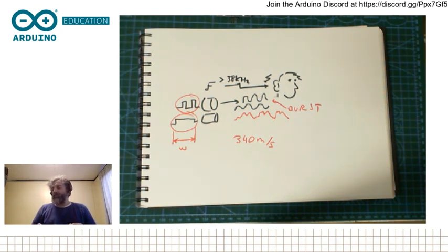The signal pin is used first as a way to transmit the burst. It sends a signal that says, okay, get started. And it's then transformed into an output pin so that it can talk to Arduino and tell Arduino the pulse in a certain way. This is something that many people don't know, but in Arduino you can actually write your program so that a pin is first an input and then an output.